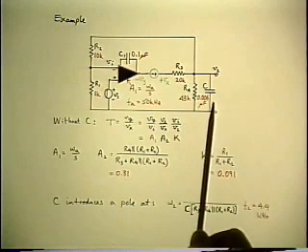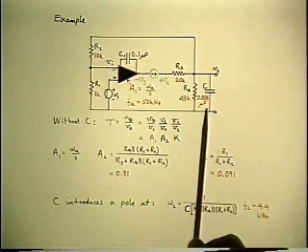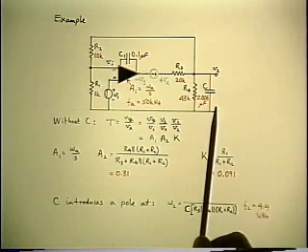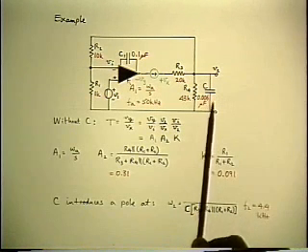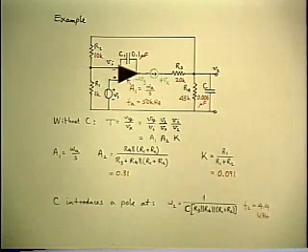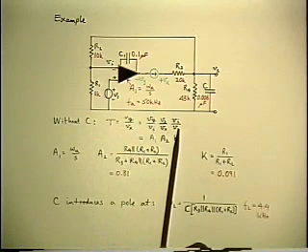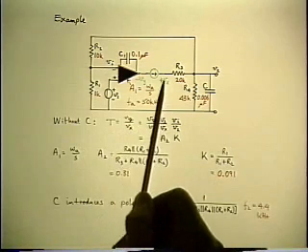So all I have to do is calculate the driving resistance to find the pole, which is the RD, which is found under conditions of zero input and substitution of an independent source for the capacitor. And again, the only catch is you've got to be careful to identify properly what is the input. And we're solving for the loop gain. The input to the loop gain is the quantity in the denominator, which is Vx.